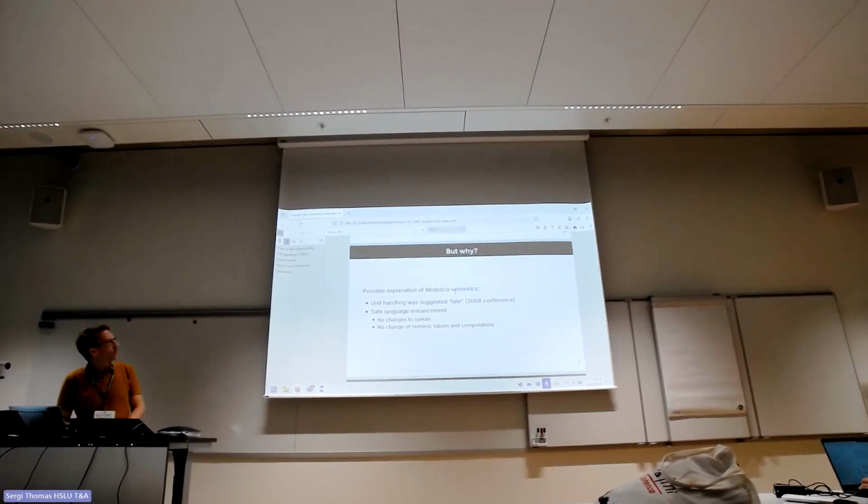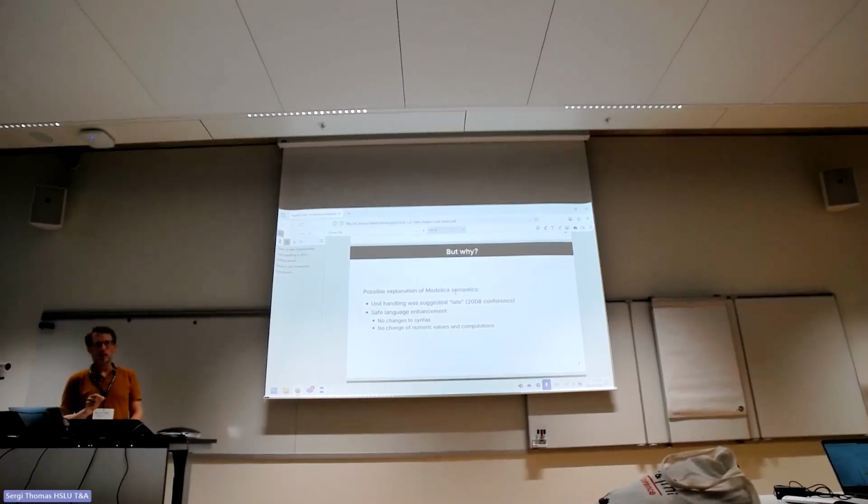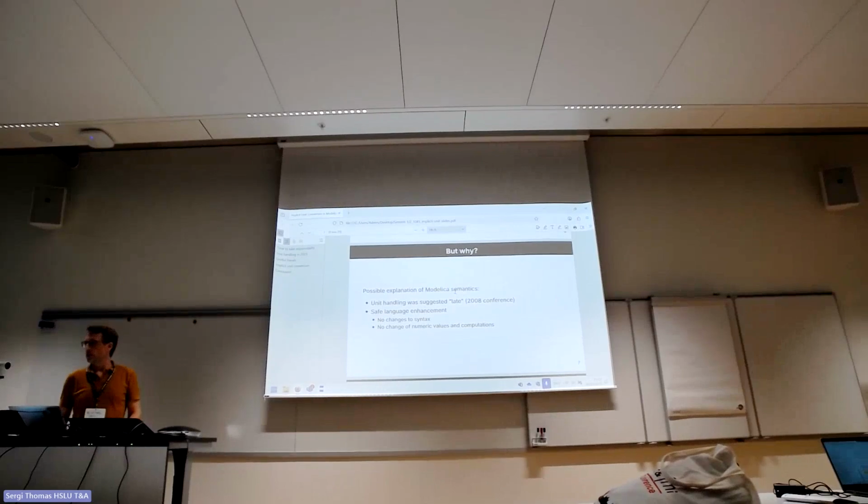I'm just guessing why we ended up like this in Modelica, and I think it was because unit support was not in the language from the beginning. As Hans pointed out, it was suggested by Henrik and others in 2008 at the conference. And it was done then in a way that would be a safe language enhancement. There were no changes to the syntax, only these new added attributes. And more importantly, there were no corresponding changes to the underlying numeric computations when you start using units. So you get some additional sanity checking of the units, plus the benefit of using display units.